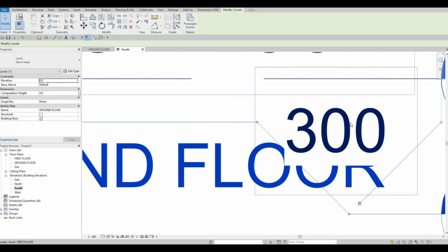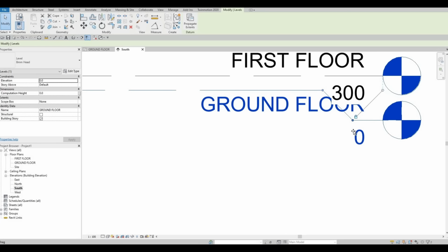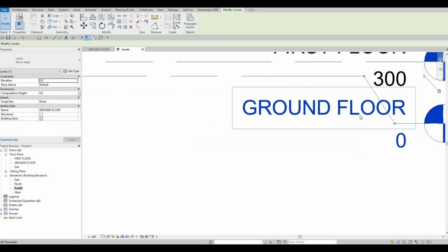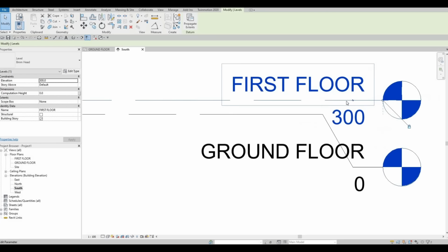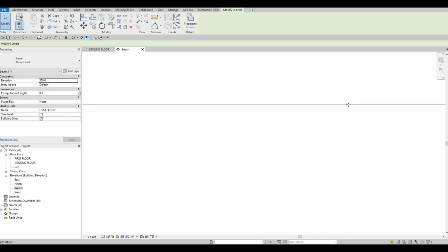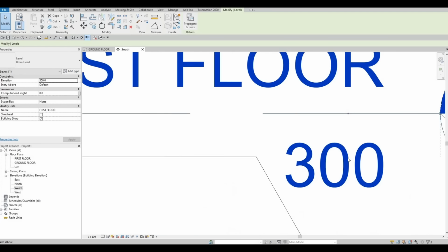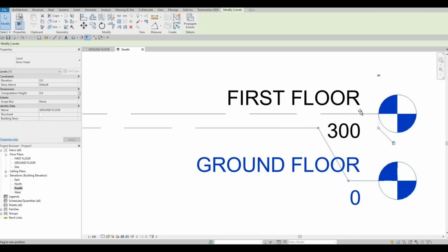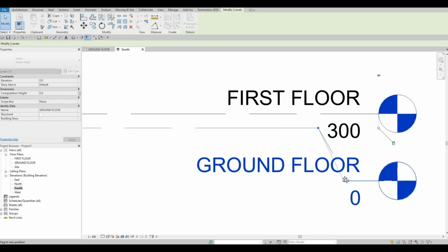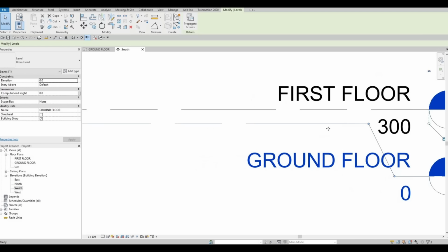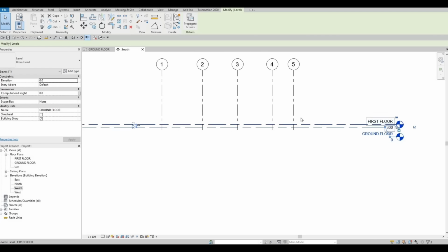So you'll be able to add an elbow in order for you to fix any overlappings. You can see a very small zigzag there, and you click that to add an elbow. This elbow, you will be able to put it upwards or downwards or whatever direction you deem best for your layout and for you to be able to read it.